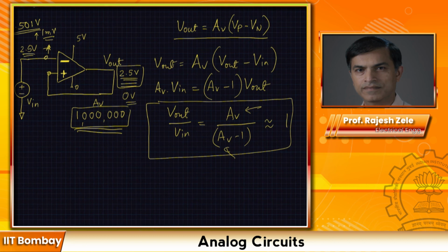And the positive feedback generally, in the amplification type of situation, is not a good thing, because it would latch up the system one way or the other. In the speaker and microphone example that I gave you, it won't latch up. You will just hear a really loud tone, which is the other mode of operation of the amplifier, which is like an oscillator. Okay, we are going to touch upon that later on.